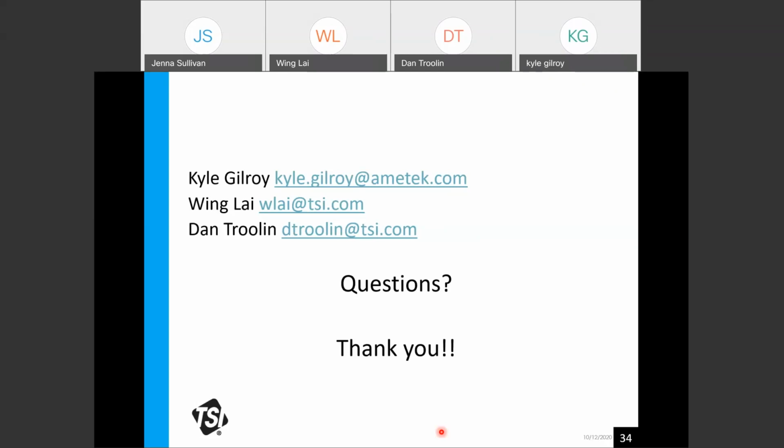Yeah, I was just going to add a point to that. That's a great question, and where you can find that in the camera specification is you look for, as Wing mentioned, the straddle time, which is basically our f sync signal, which has a really short readout time, on the order of hundreds of nanoseconds, and then some cameras on the order of 1 microsecond, right? Good point. Thanks for mentioning that, Kyle.